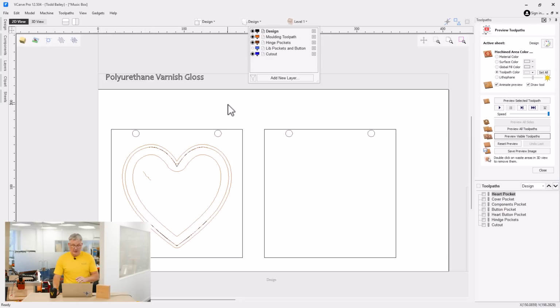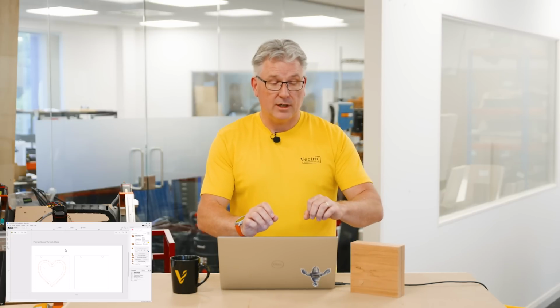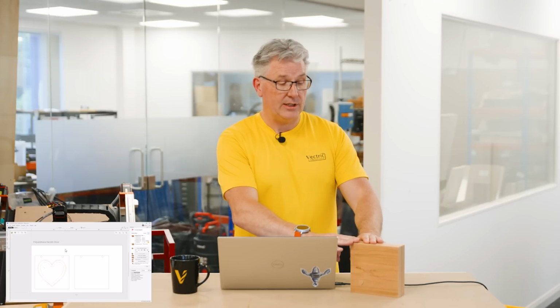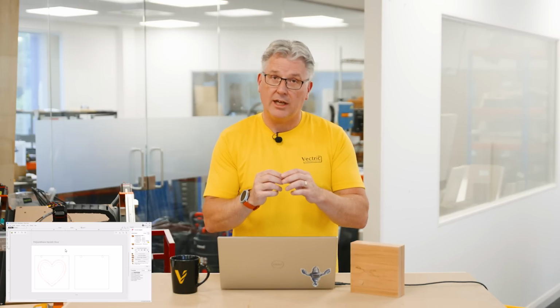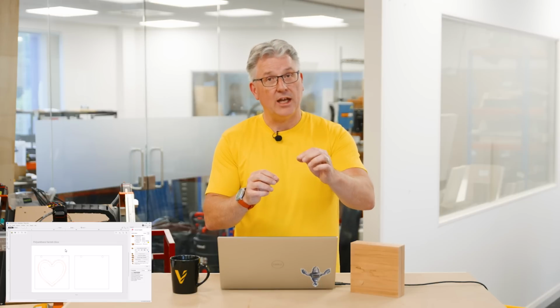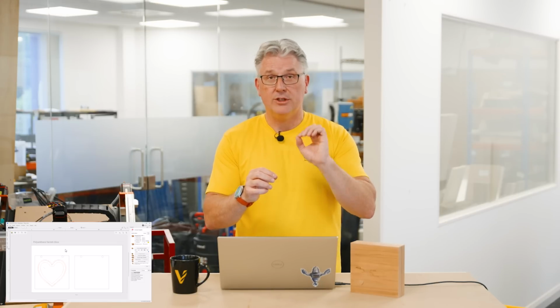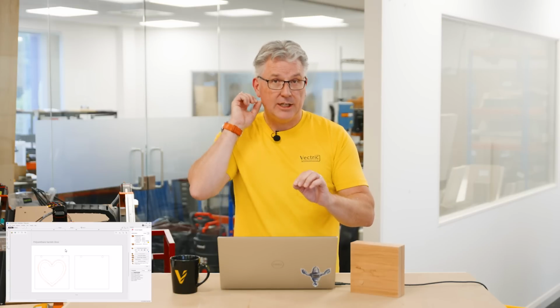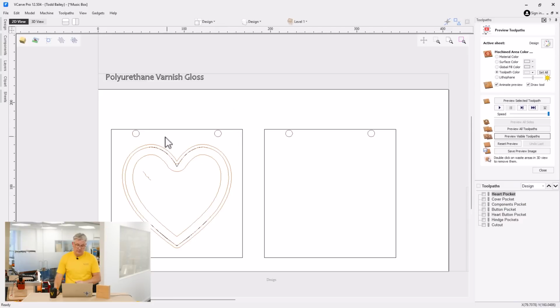Now, these are those hidden hinges that I used, and what's nice about using a CNC to make something like this is you can be very accurate. And with these hidden hinges, I had to be really accurate with the position of the holes, 1 millimeter from the edge of the box top and bottom, and then also the depth had to be perfect. And so in this case, using my CNC, that was really easy to do. So I laid those out where they should be. So that's what those 4 holes are for.